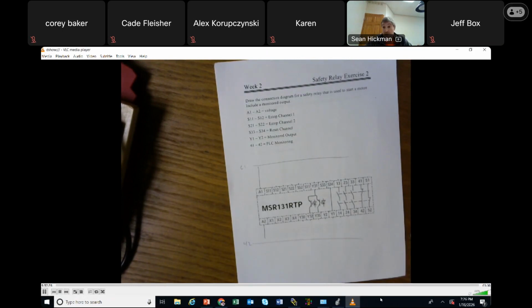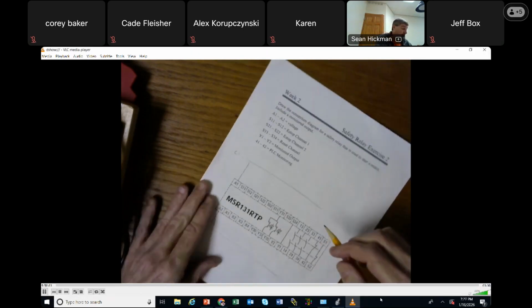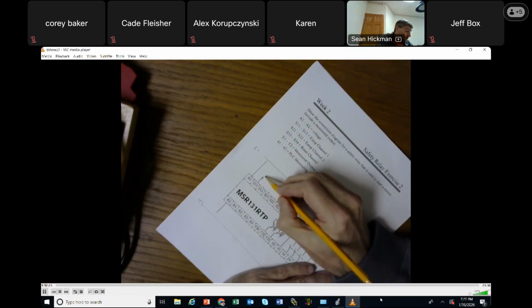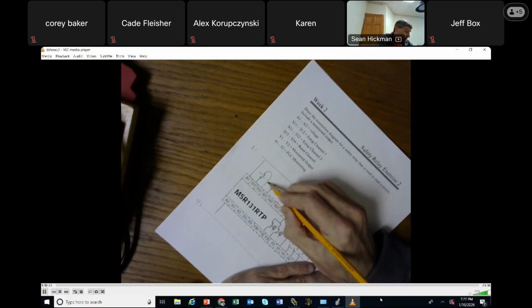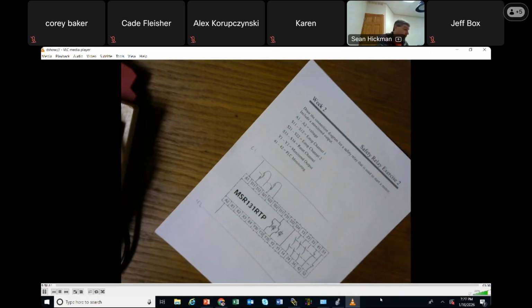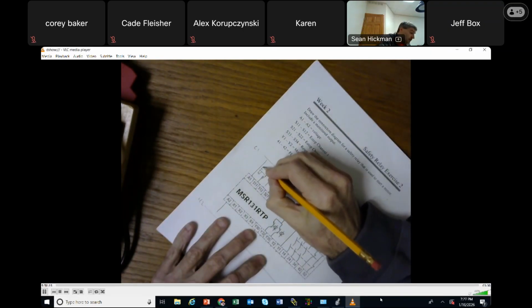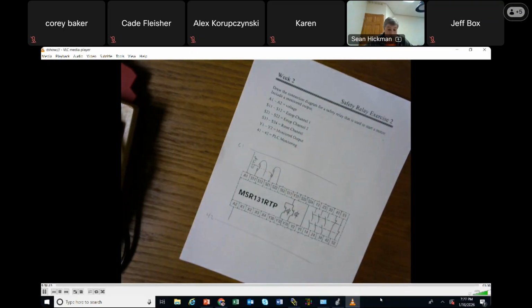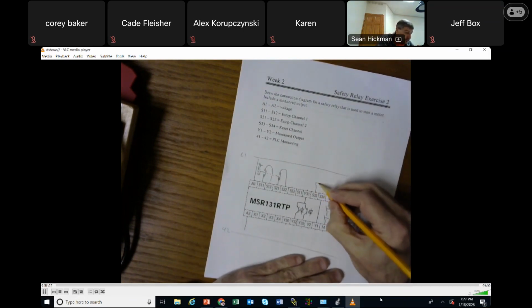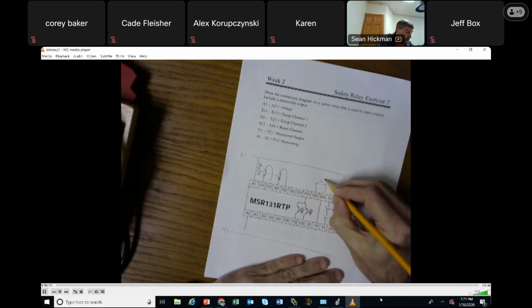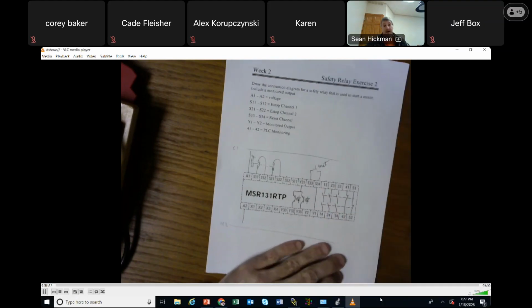We still need a dual channel E-stop. We want to hit the E-stop to stop it, and we learned the way to do that is just take this one, which is closed, and wrap it to there, which is just a dual contact running to there. So this is my E-stop right here, which kills it. It says you're still gonna want to reset. We'll put a reset on it, which is 33. You think about this reset, it's almost like an on. So there's my push button for my reset. Wire that, reset on.